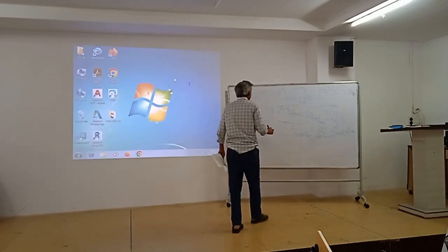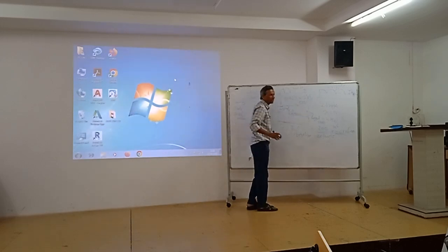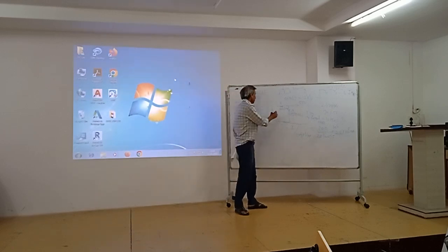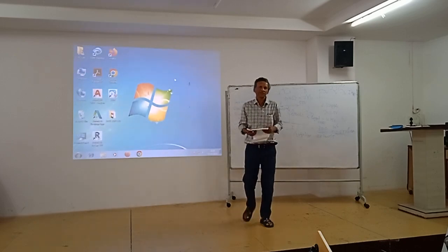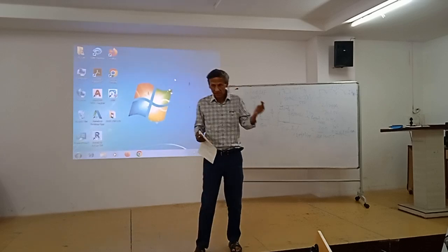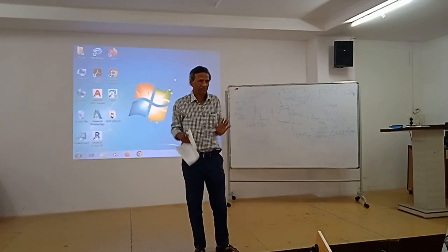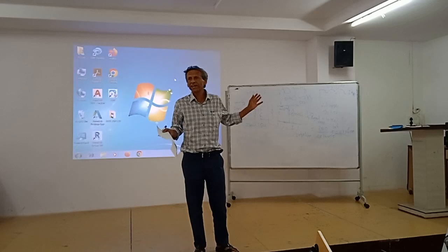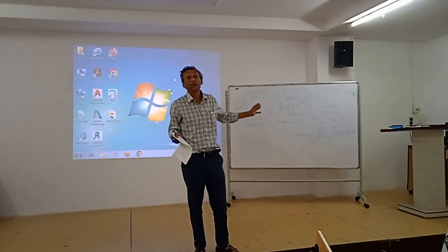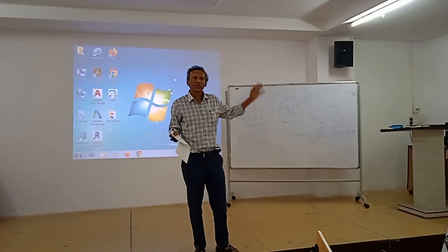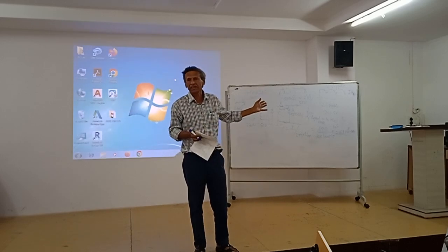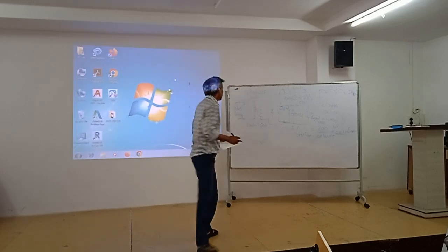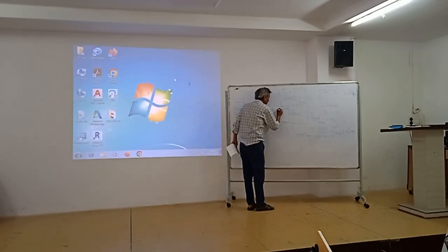You have to find out RC time constant. This is R and combined C. So it is an exponential charging. But can I put this forever in series? Inrush issue is now gone. Loss. Current loss. Power loss. Heavy loss. You can't imagine this. Let it be 1 ohm. Current is there. Yeah, 200 ampere, 200 square into 1, 40,000 watt loss here. So it's useless. Let it be even 1 ohm, not even 10.